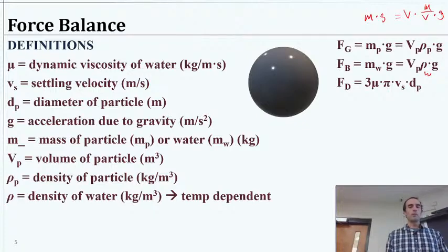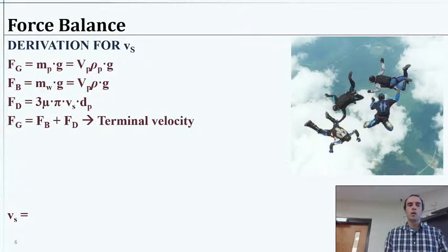We could convert to some other unit, but since our dynamic viscosities are typically given in kilograms, meters, and seconds, and acceleration due to gravity, we should remember, is 9.81 meters per second squared, we already have a lot in meters, seconds, and kilograms, so we're going to keep it that way. Whenever we solve a problem for finding a sedimentation velocity, a lot of the problem will just be converting the units accordingly and making sure we're set on all of that. We'll do an example problem today.